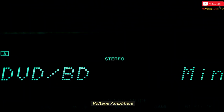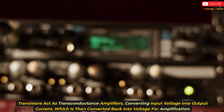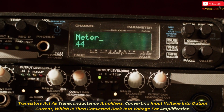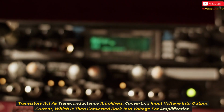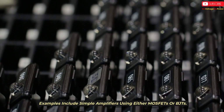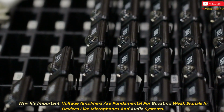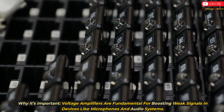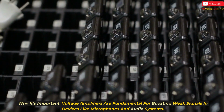Voltage amplifiers. Transistors act as transconductance amplifiers, converting input voltage into output current, which is then converted back into voltage for amplification. Examples include simple amplifiers using either MOSFETs or BJTs. Why it's important? Voltage amplifiers are fundamental for boosting weak signals in devices like microphones and audio systems.